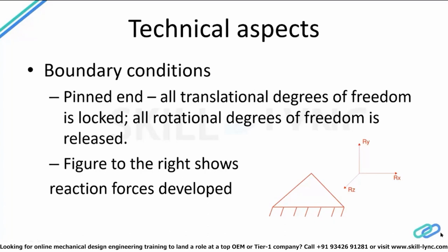The first one that we could look at, and one more thing I would like to bring up here, is that any support would induce a reaction load only in the direction in which it is locking or restraining a particular degree of freedom. And that's how that stress is developed in the support.